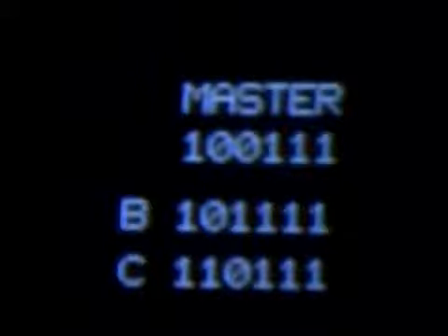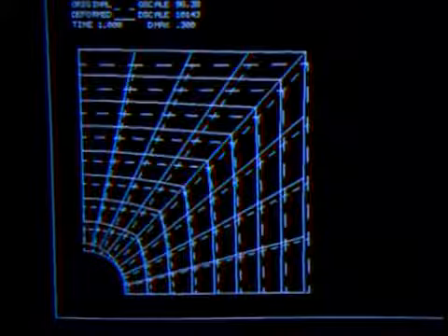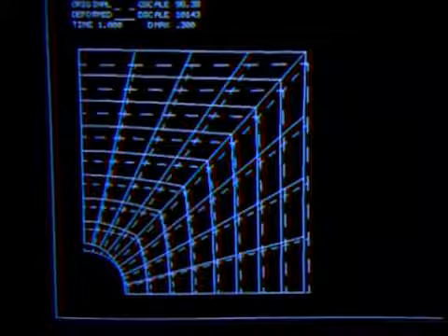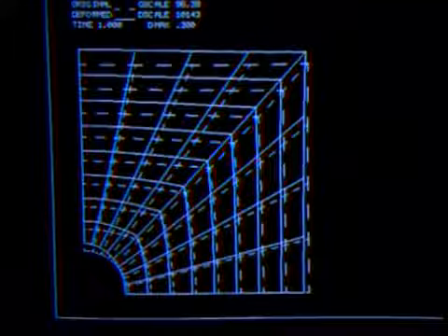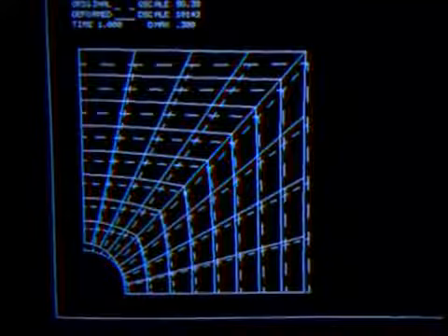C on the vertical symmetry line means now the W displacement is free. We run ADINA again, and here you see the deformed mesh plotted on the original mesh. The deformations look very reasonable. The plate has contracted horizontally, and correspondingly the hole has shrunk horizontally.